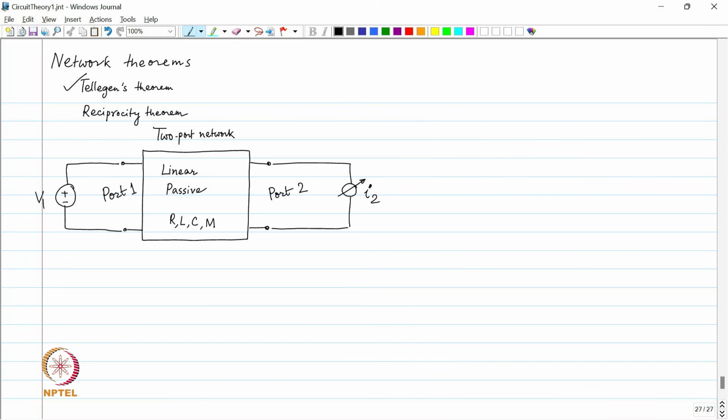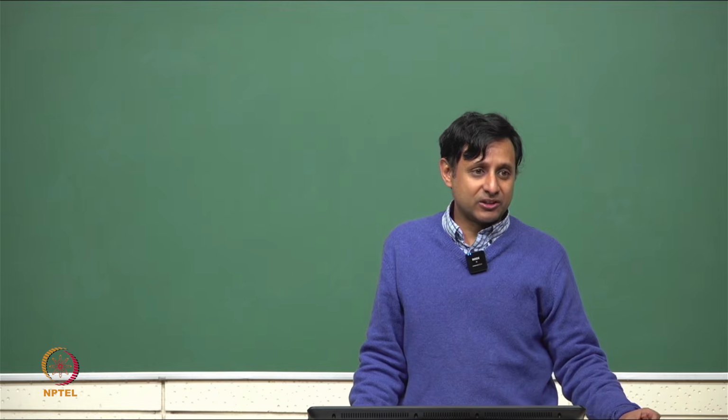What is an ammeter? Is it an open circuit or a short circuit? Short circuit. Why? Can it be an open circuit? No, because no current goes through an open circuit. What is there to measure? An ammeter will have to measure current. So, it is a short circuit.